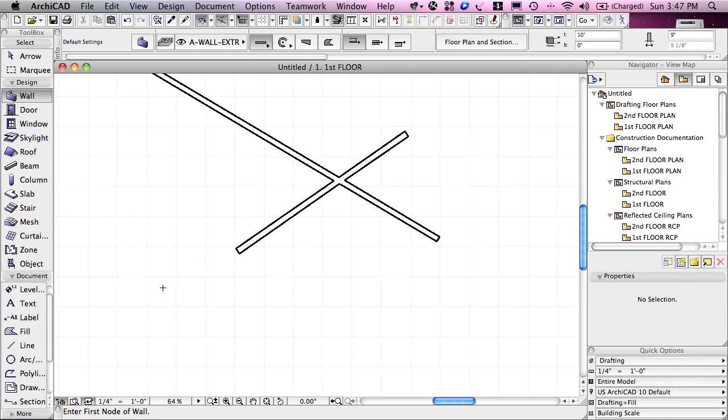Now if I want to draw something straight, instead of just doing it in any arbitrary direction, I can look at the guideline. That dashed line that you see is indicating that I'm on the axis line, in this case the x-axis. And if I go up this way, you can see that the angle is 90 degrees and it's on the y-axis going up and down. So I can draw something very easily straight simply by allowing my mouse to stay close to that line. You notice as I move it left to right, it doesn't change until I get far enough away to leave the gravity range. When I bring it closer, it snaps into position, so I can know that I'm going straight.